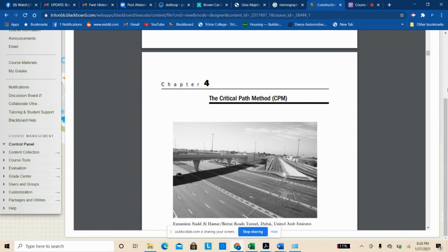You're supposed to store the hardwood material in your house for some amount of time and let it come to humidity equilibrium with your house, so when you put it down it doesn't suddenly absorb moisture, buckle up and start popping. That would be like a lag, what we were just talking about. You don't just get the material delivered; you have to wait for it to come to equilibrium, and you might have 3 weeks right there.